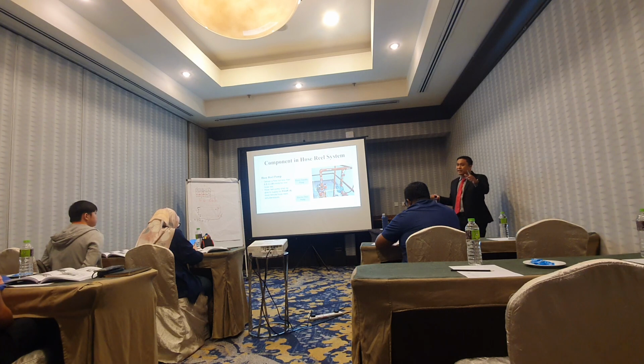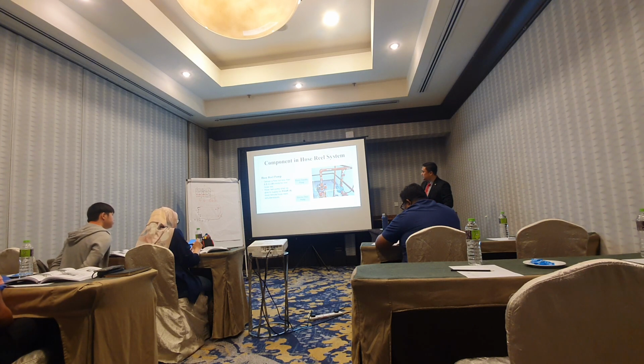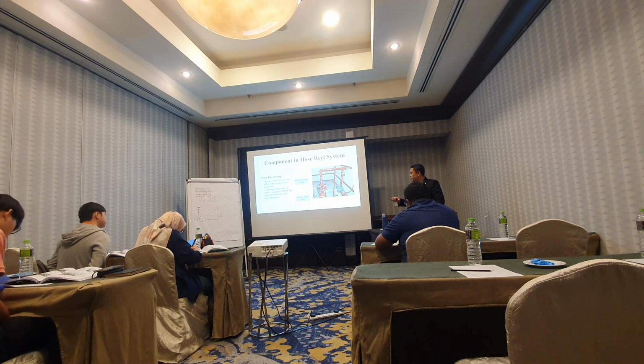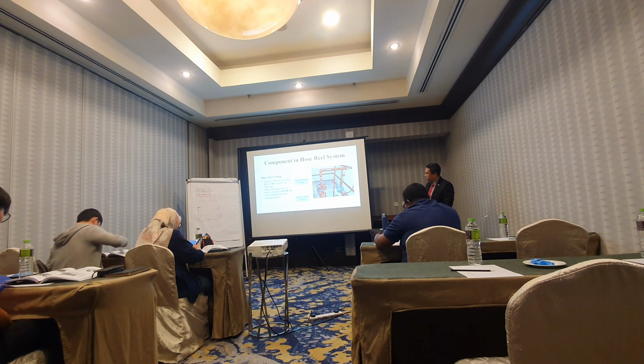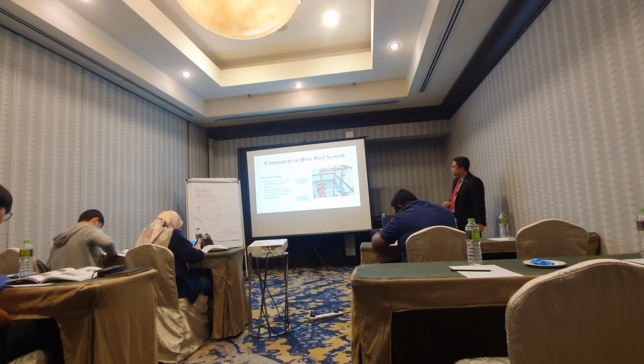Tu tadi water tank kan. How you get the 7,200? This is because of this requirement lah. So from the calculation, if we do the design, we design for the pump to cater 4 hose reels at the most remote area to operate at this flow rate.